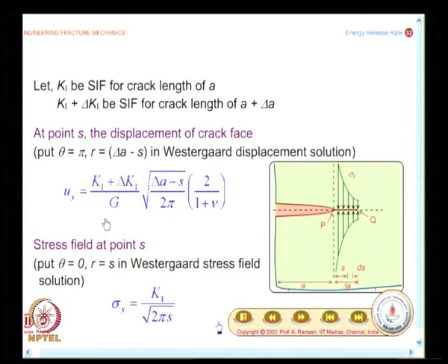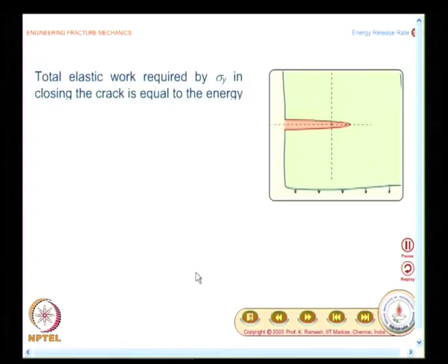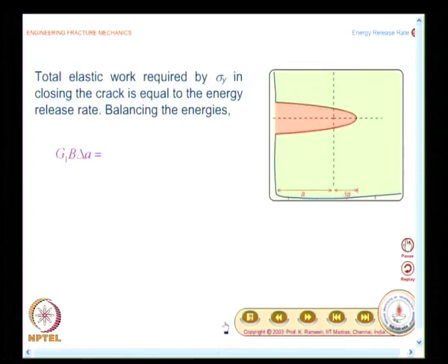So, now I have to carefully write the energy expression, and deliberately for this exercise I have taken a plate of thickness B. So, when I take a plate of thickness B, the delta A is B into delta A. So, I have to evaluate G1 B into delta A, which I have already mentioned in many of my subject developments. For certain cases I will use unit thickness, certain cases I will do it with constant thickness b, so that you get familiar with different forms of expression.